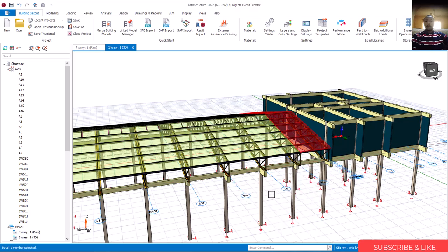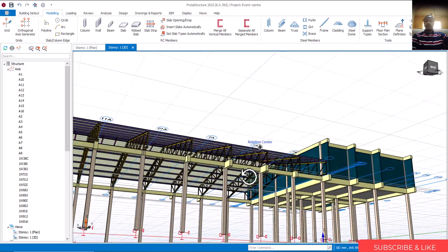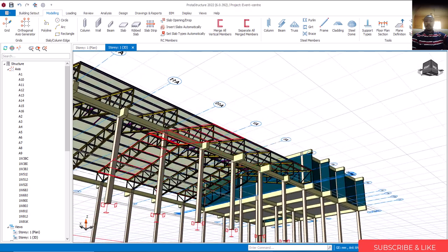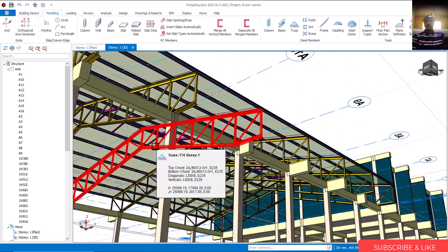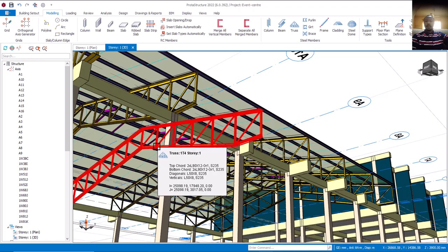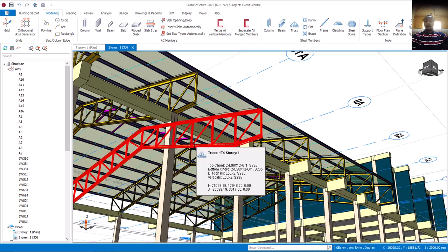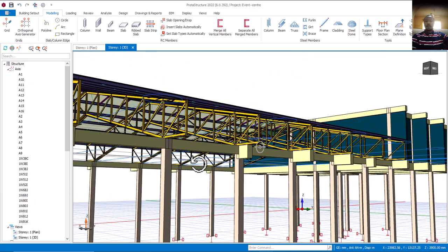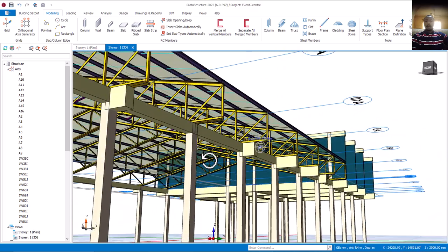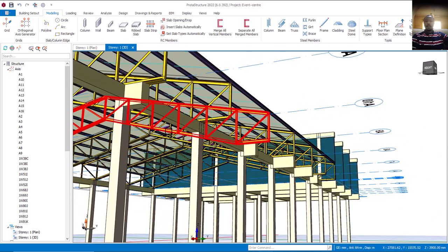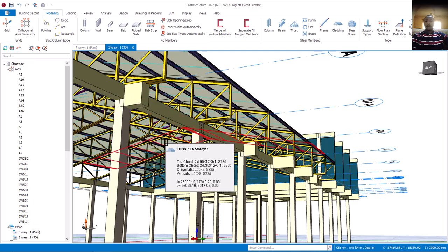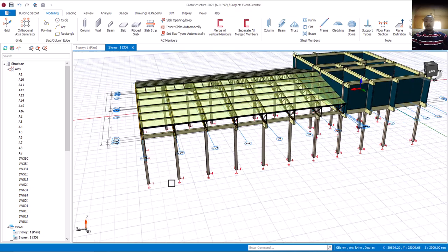Now what I'm trying to say is that the loading at times, in some places, you can see some speakers, even big TVs, can be hung on these members. So in such a case, if they inform you beforehand about the way they are going to put their speakers, it will also determine your loading of this place, because the weight of those speakers is going to drag these members. You have to design for it. All right, that's fine.